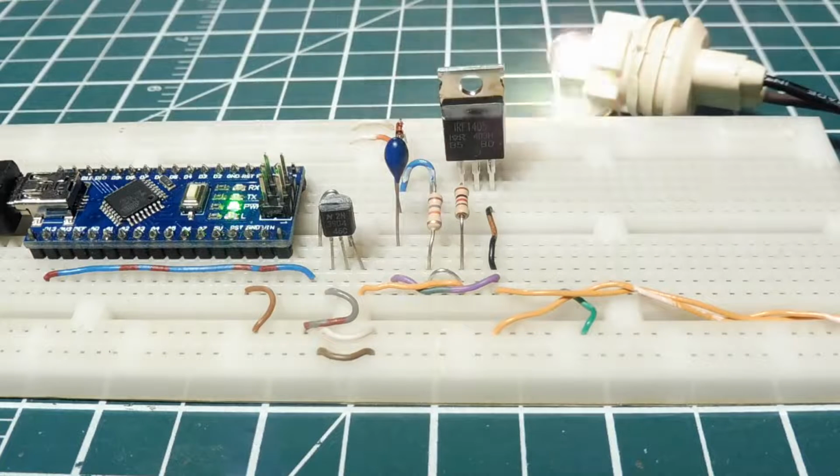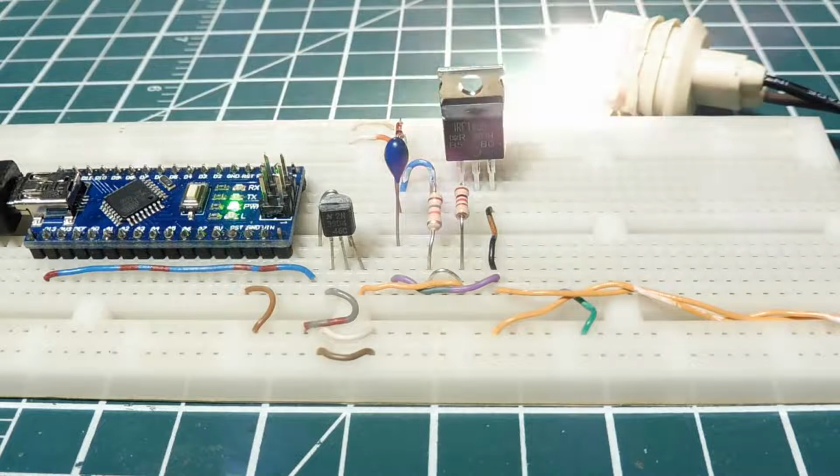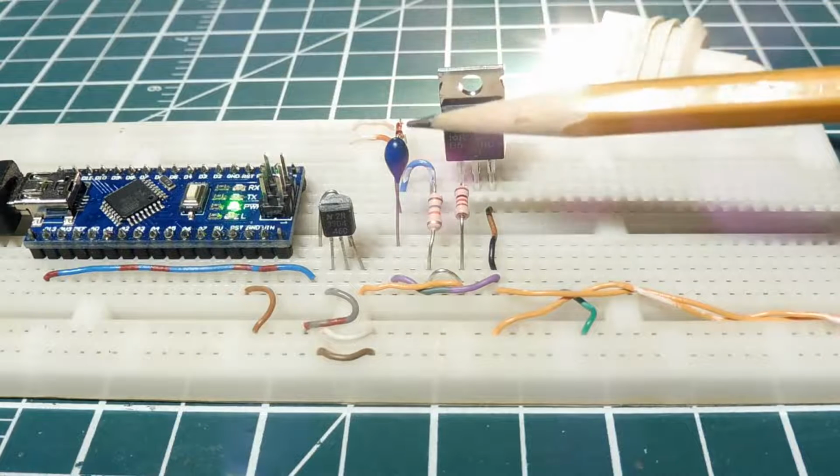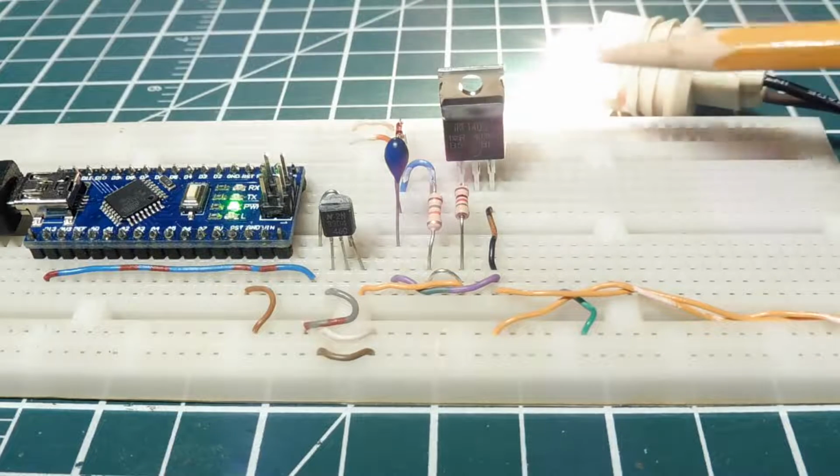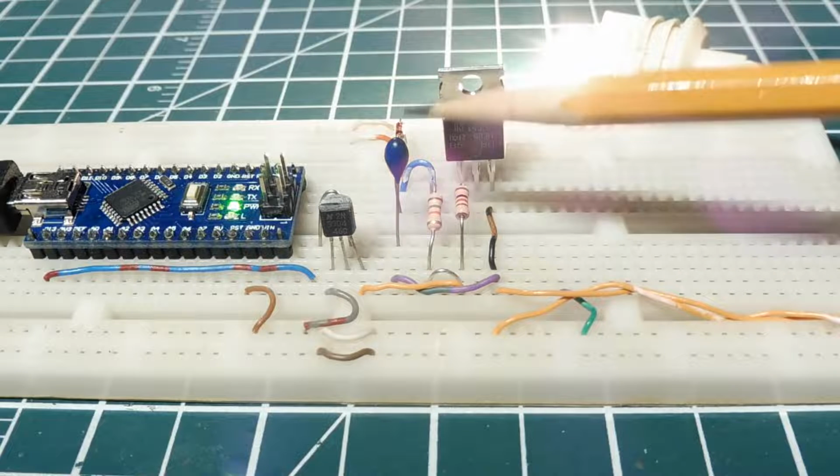Now there's one drawback to the circuitry. If I turn off the blink circuit, so it's on steady, right now we're feeding 24 volts to the gate of the MOSFET. 12 volts is coming from the power supply. Another 12 volts is coming from this capacitor, which is charged up to 12 volts. So the capacitor and the power supply are in series to give 24 volts.